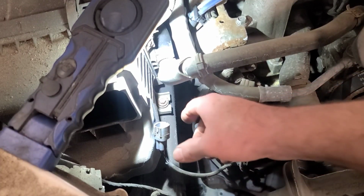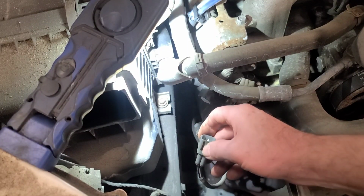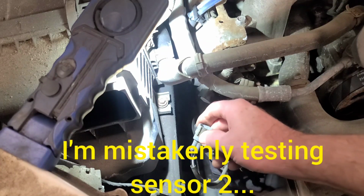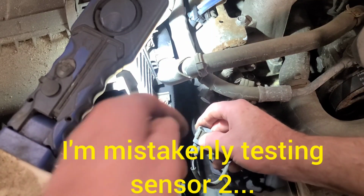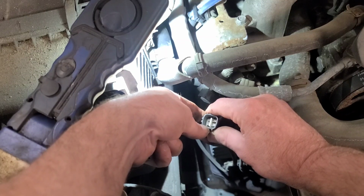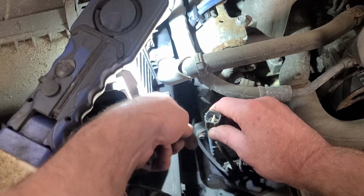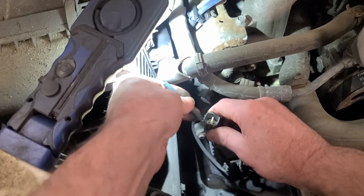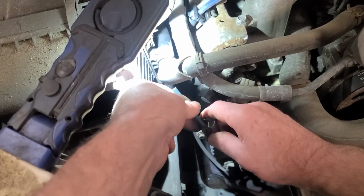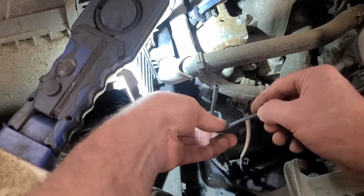So if you take the air induction inlet off, you can disconnect the oxygen sensor connector. Bank 1 sensor 1 is the first oxygen sensor in the exhaust flow, so this one here. If you look at this connector here, you'll see there are 4 wires to it. 2 of them are gold plated. The gold plated pins, I would assume, are the oxygen sensor themselves. The other 2 pins are for the heater. So we're going to just quickly measure continuity across this heater circuit with a couple of test probes. Got the ohmmeter set up here.